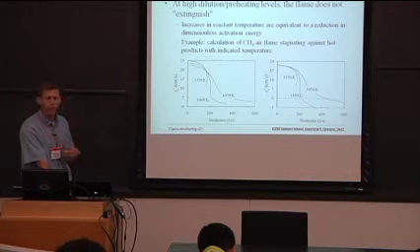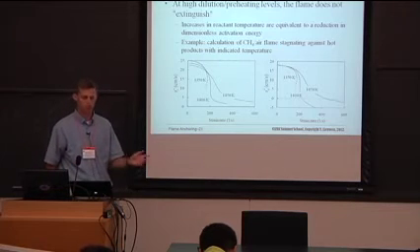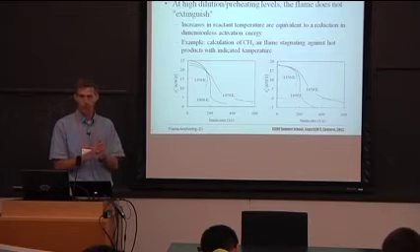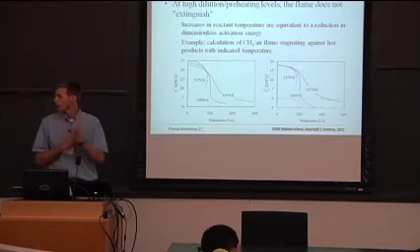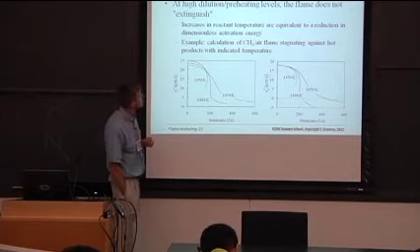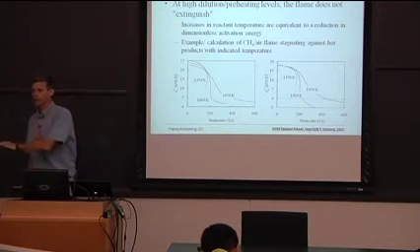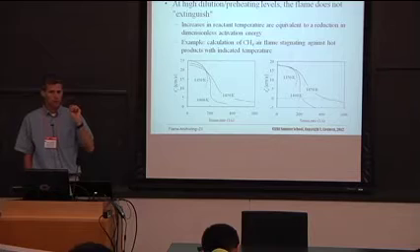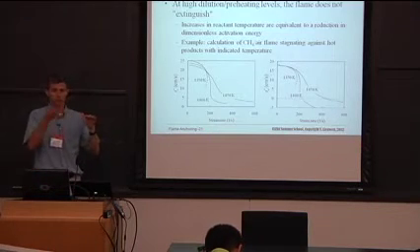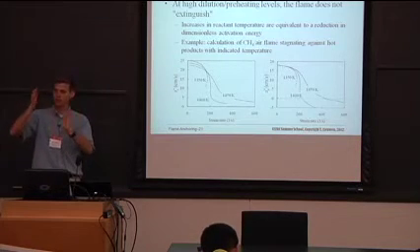What I'm going to talk to you about is that blow-off doesn't become an event like it does in a simple Bunsen flame, where you have the flow, you have a flame, you increase the velocity, and bang, flame's gone. Blow-off becomes a process. And in order to illustrate that, what I have here are some calculations. Basically, why do flames extinguish? Think back to your combustion theory class. Extinction is fundamentally a fact that you have high activation energy. High activation energy gives you this S-curve. You guys remember the S-curve? S-curves mean you have distinct extinction and ignition events.